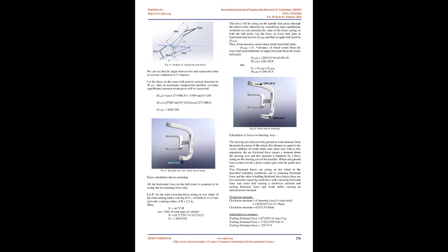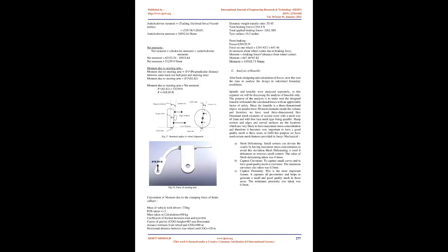B. Weight of the knuckle. Weight of the knuckle is very crucial as it adds up to the unsprung mass of the vehicle, so the design must give sufficient strength with the least possible weight. C. Material to be used. Material selection is also a very important parameter. It defines the volume of the design and also the weight according to the strength of the material.